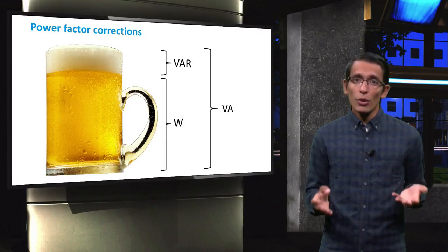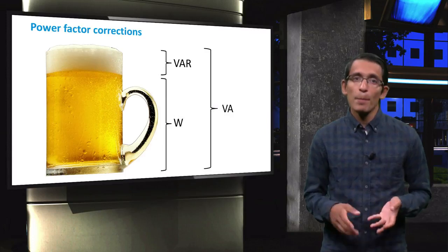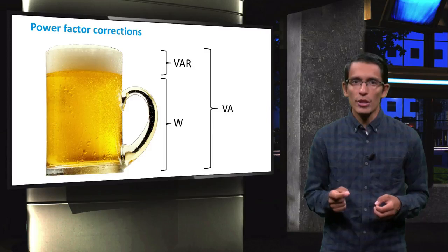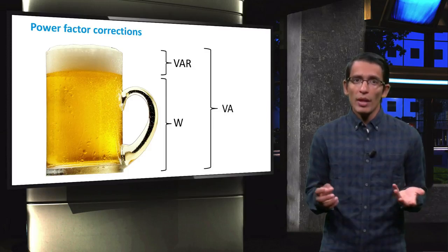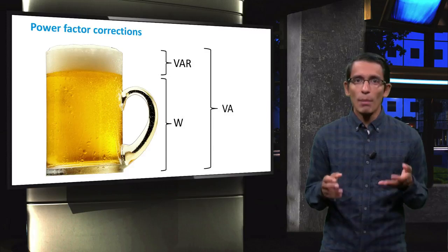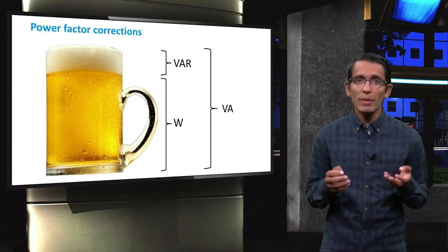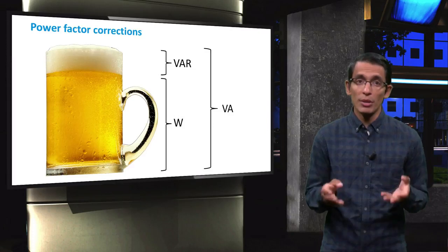Well, there are control circuits in place to reduce the amount of reactive power in transmission lines. However, these circuits are specifically tuned to a predictable power source. With PV, the power output is not predictable. This means that the amount of reactive power may be greater than desired, reducing the power factor of a grid. This is something grid providers have to become more and more aware of as distributed generation becomes more substantial.